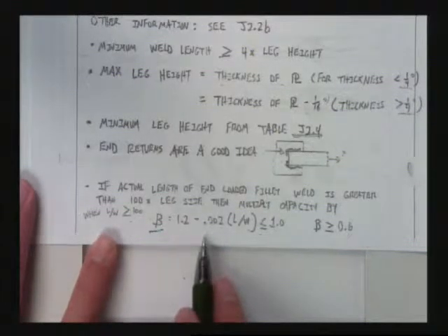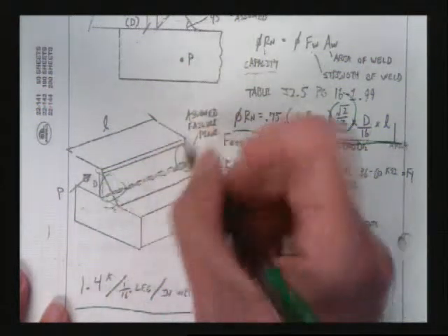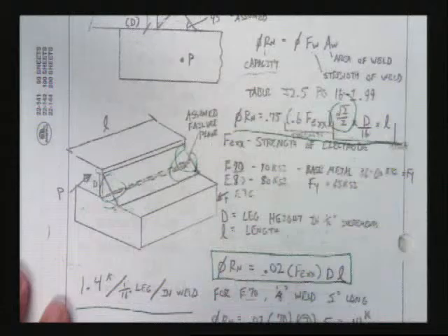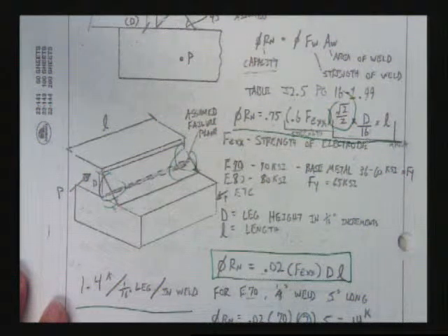Now, one could argue that possibly what you should do is load the system up, calculate what the actual strains would be here, calculate what the strains would be here, see if you've exceeded what your strain capacity is for your weld, right? Double check that. That's kind of what we do in reinforced concrete. We look at over-reinforced beams or not, okay? We're doing similar type of calculations, okay?